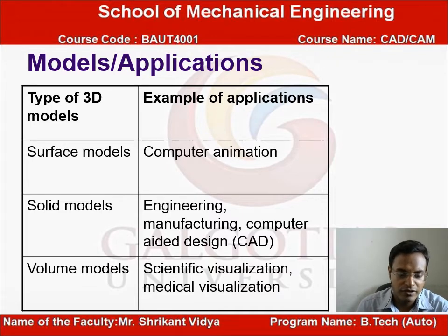Then the surface model. A surface model is a set of faces. A surface model consists of wireframe entities that form the basis to create surface entities. In general, a wireframe model can be extracted from a surface model. A surface model consists of different surfaces, so we can extract the wireframe model from the surface model by deleting or blanking all surface entities.